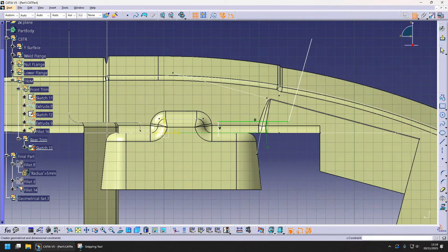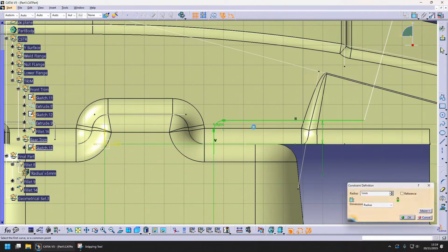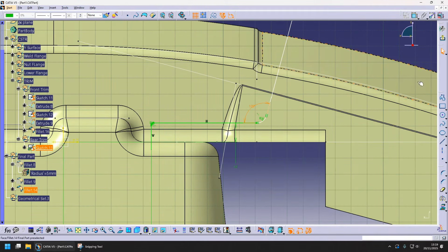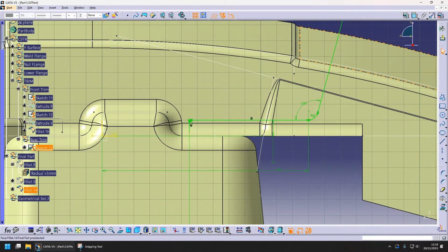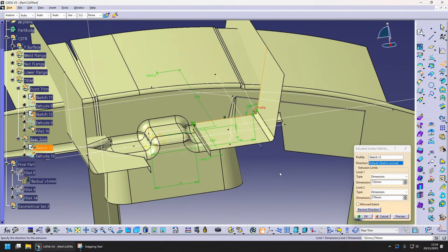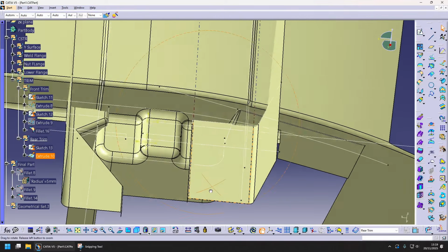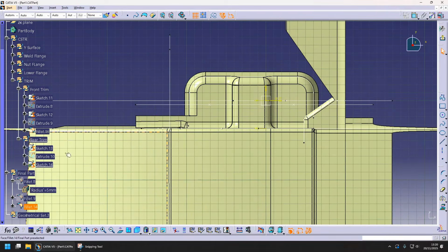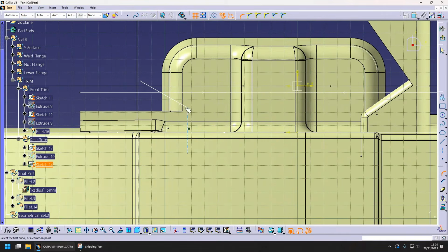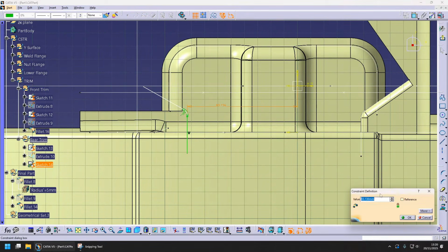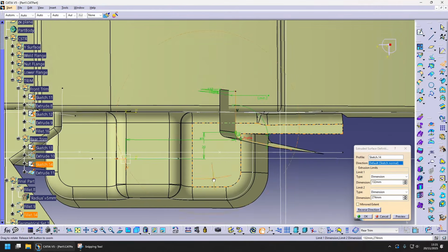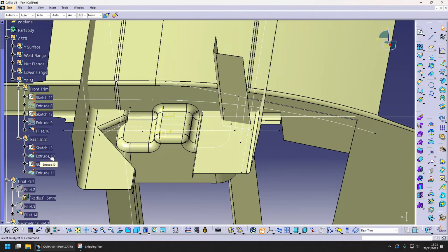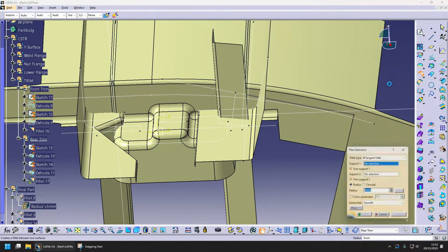Again, not sure which is the front and which is the back. So we create this sketch again. The top surface, the forward line is gonna be angled this time, from what I can tell in my reference picture. Okay, we extrude this in one direction, and then we create the other sketch. Make sure we constrain it well. This just trims that little part of the corner there. We extrude this in Z, and then we fillet the two together.